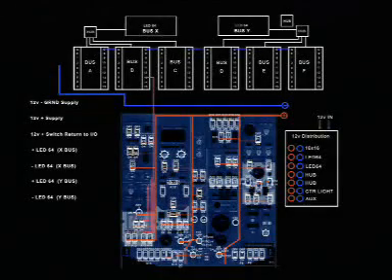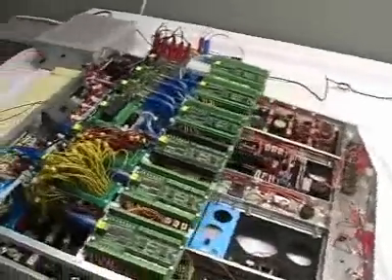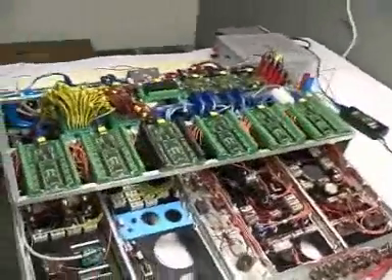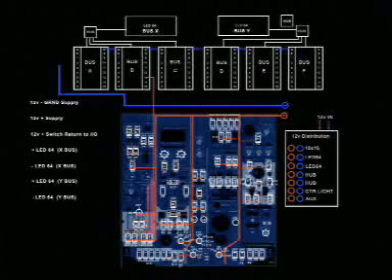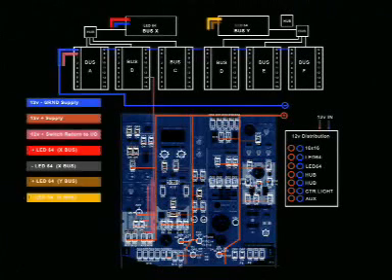In order to keep track of the wires, in fact over 1.2 kilometers of wire were used on this 737 overhead, a colour-coded system was used. Blue for ground, brown for the positive switch supply lines, and pink for the positive return to the I/O card.